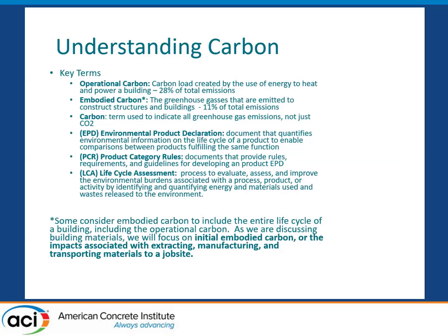Understanding the carbon impacts and the terms, there's operational carbon. That is the carbon load that is created from using energy, heating, powering buildings, and so forth. Then embodied carbon is the embodied greenhouse gases that are emitted during the construction process of buildings and the making of that material. And carbon is a general term that's used for greenhouse gas emissions. It's not just CO2, but it can also contain methane and other equivalencies.